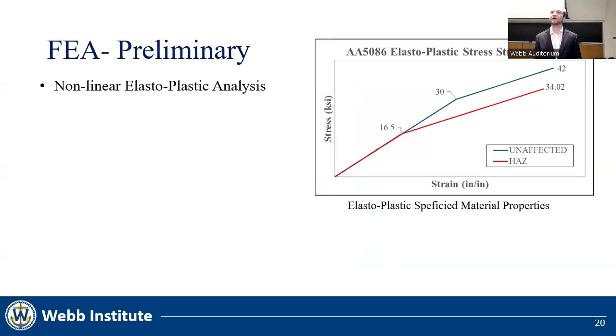This analysis was an elastoplastic analysis, and its bilinear nature can be seen above, with strain on the x-axis and stress on the y-axis. Instead of a complex material property curve, basic material properties are input, and the material yields along its Young's modulus, E, until its yield strength is reached, at which point it yields along its assumed plastic modulus, H, until the ultimate strength is met. The plastic modulus was assumed to be half of the elastic modulus for this study.